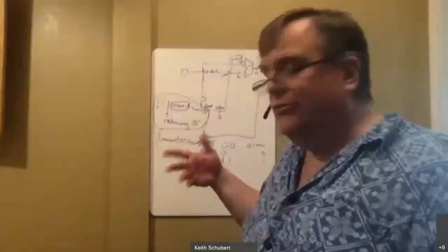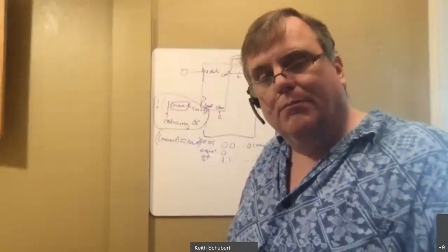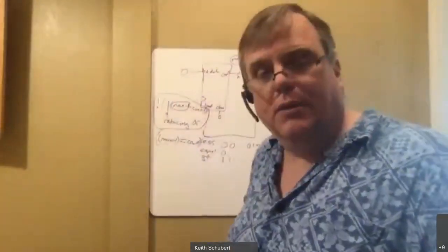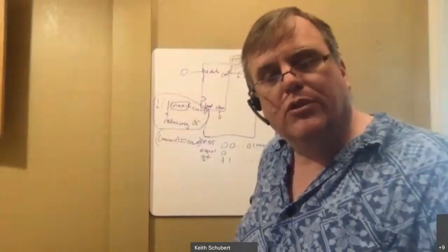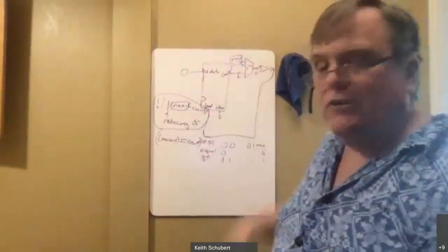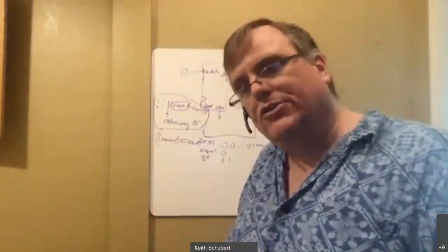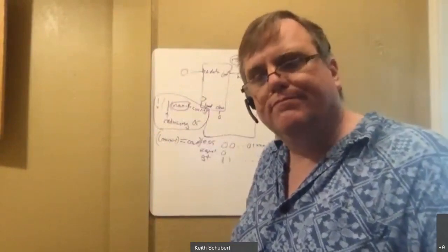So for a small counter, if it's only like 2 or 3 bits, it might make perfect sense to build it not by doing one of these high level ways, but maybe you actually do a Karnaugh map. So you get a more efficient small build. An adder subtractor definitely works, but it's a fairly complicated circuit. A Karnaugh map could potentially get you a smaller one.